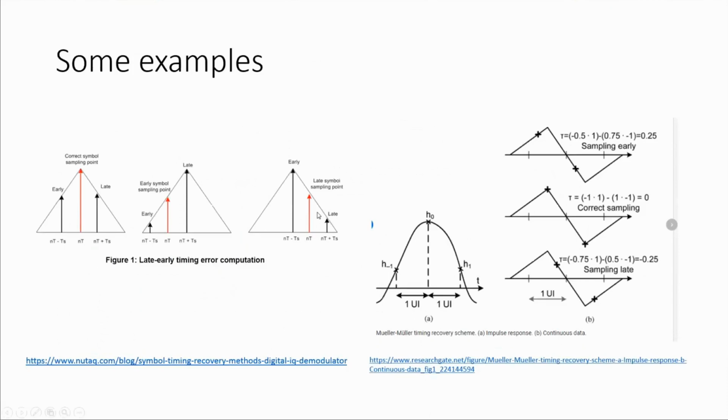So the thing that really messed me up on these, and I just want to reiterate that, is that, like I said, if your clock rate is 1 clock per second, it's really important to understand that this is 3 clocks per second. No one says that anywhere when you read this, and you're like, how does this work? That's important. These triangles come from a match filter and an integrator, which we didn't talk about, but that is a crucial concept to understand how these waveforms are created. But if you know that you have more samples per unit interval than your data, then this will make a lot more sense.